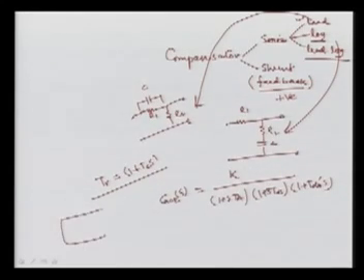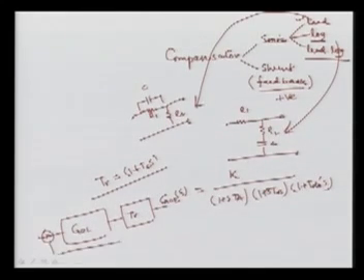Means we are having this G open loop, and now we are using the TR, that is a compensator, and then we are having this loop. Normally we put this one on this side because the output here is simply voltage. So if this is multiplied here, we get, let's suppose, 1 plus TC, that is the time constant of the compensator. What we can do is set the value of this TC in such a fashion that we can cancel any of our open loop poles here.